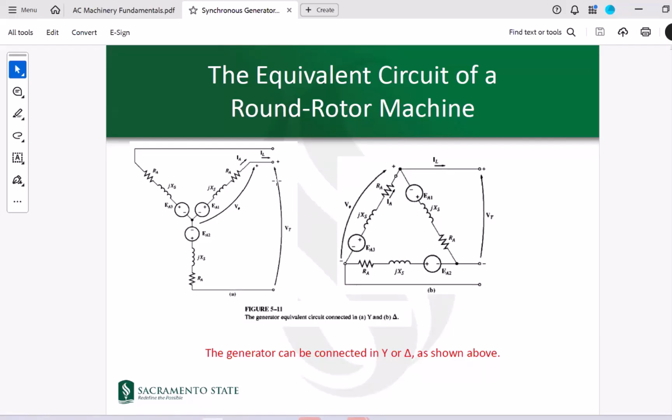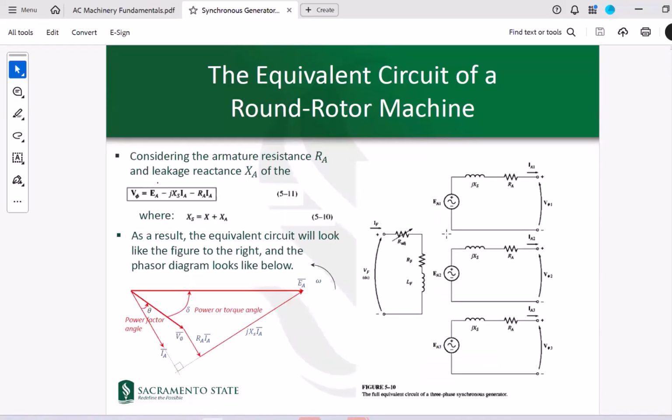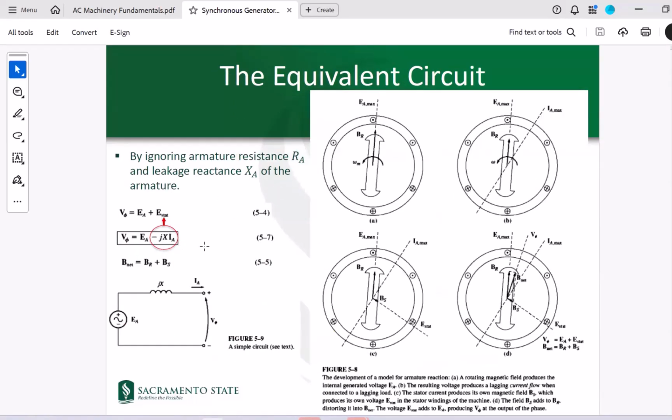The terminal voltage here would be related to the phase voltages like this. You have to add up these two to get the terminal voltage. In other words, if your system is balanced, the terminal voltage would be square root of 3 times the phase voltage. I recall that sometimes I called this V phi the terminal voltage in my previous explanations.